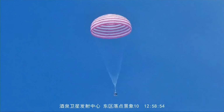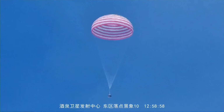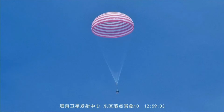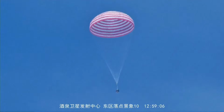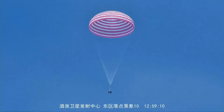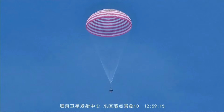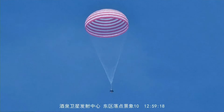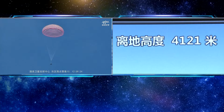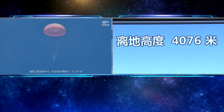The ignition, very good question, very professional. Just on the bottom of our re-entry capsule, we have a device called a gamma ray altimeter. It emits gamma rays to the ground, and with the reflection, a receiver measures the time. So we can have a very precise measurement of the distance between the bottom and the ground. It will send signals to ignite the 4 rocket engines and slow down the vehicle to, as mentioned, less than 2 meters per second. Right, and that's automatic? Yeah, this is completely automatic.